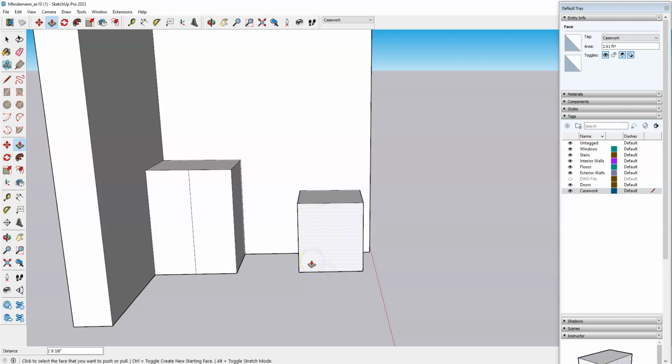If we look at the cabinets up here at the front of the room, I don't know if you can see them very well. They don't have the filler on the end because there's nothing restricting them from opening on the sides. But if these cabinets were over there against that wall, they would need a filler panel to be able to open up. That's true for lowers, uppers, full height cabinets, anything.